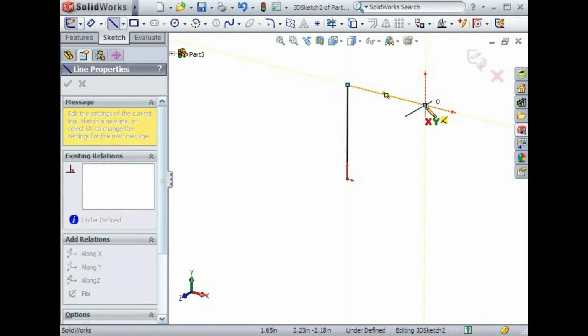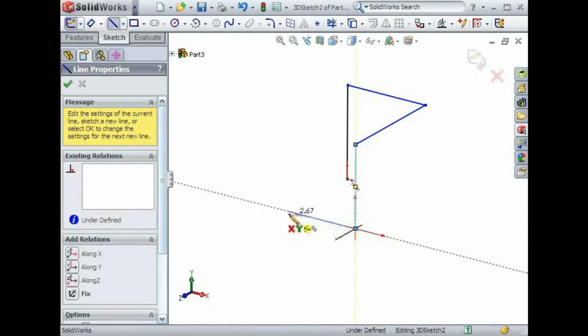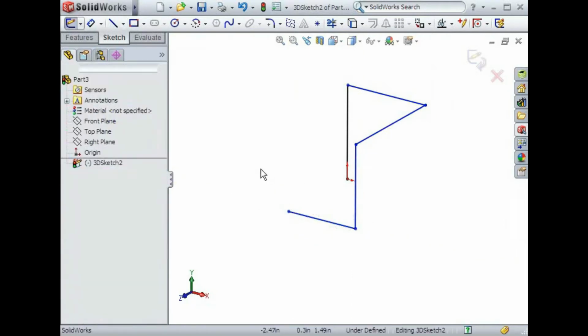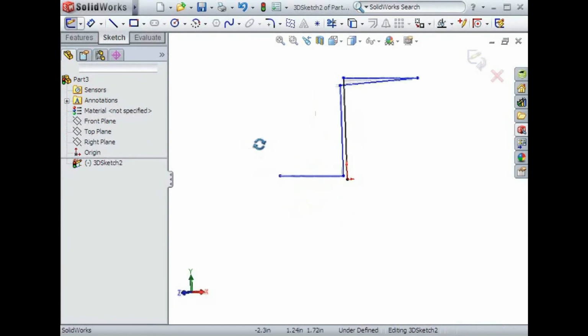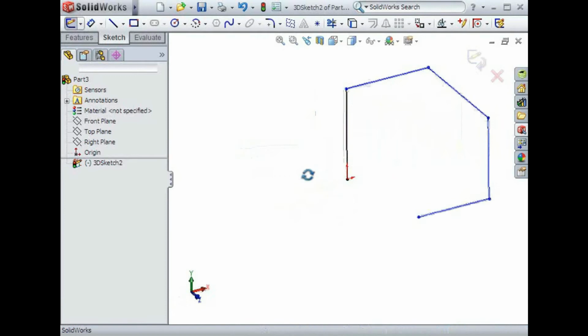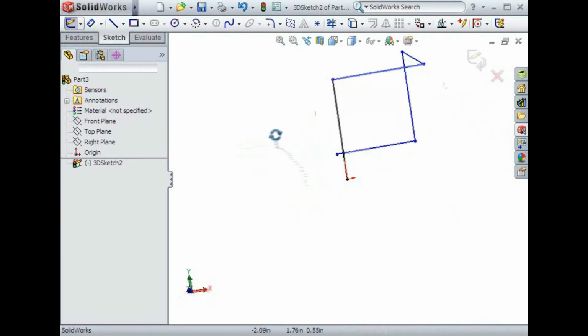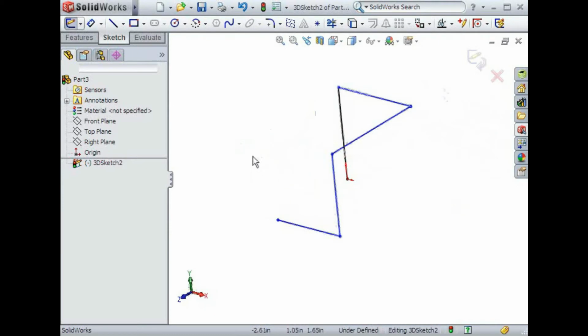Let's break out of the 2D plane by pressing the Tab key, making the YZ orientation active. Now, I'll sketch a segment in the Z direction. Using the Tab key again, let's make the XY orientation active again, and sketch a segment in the Y direction. To complete this simple example, let's add a segment in the X direction and turn off the Line tool. You can see as I rotate the sketch that I've got a 3D structure that could not have been created using a 2D sketch. In fact, to create this using 2D sketches, it would have been necessary to create two reference planes.